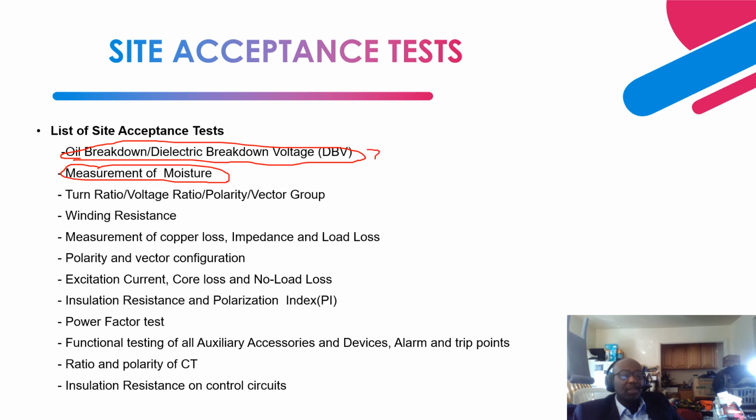This is done after installation, when you have filled the transformer with oil and energized the transformer. Let it soak for about 24 hours. That is when you collect the oil sample to be sent to two different labs to test the oil to make sure that it doesn't have any moisture from transportation and filling.